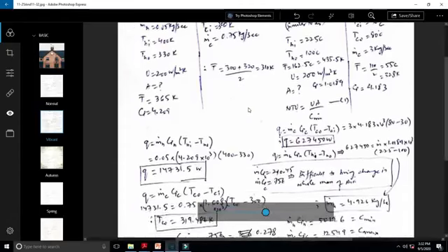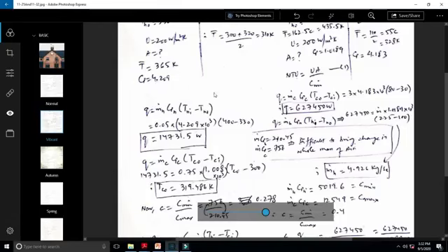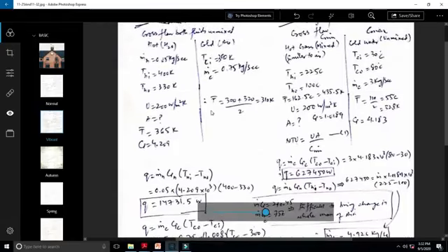So we will get the value of Cp as 1.008 then, and probably you would have understood that we put Q equal to m c delta T to find a good guess of Tc naught. We need this value so that we can find the average temperature, so that we can find the value of Cp.